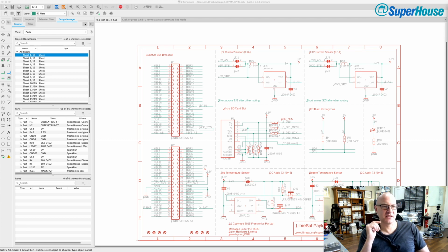What I've heard though is that there are two different types of the Dita devices. So Dita is a brand that is in the big box hardware retail stores here in Australia, and they make smart plugs that are similar to the Sonoff and light switches. But I've heard that there are two different types, and some of them have an ESP8266 in them because they've got a Wi-Fi module in them. Some of them have something else. I can't remember what. They might have a Broadcom chipset or something in them, and of course Tasmota won't run on that chip. It'll only run on the versions with an ESP8266.